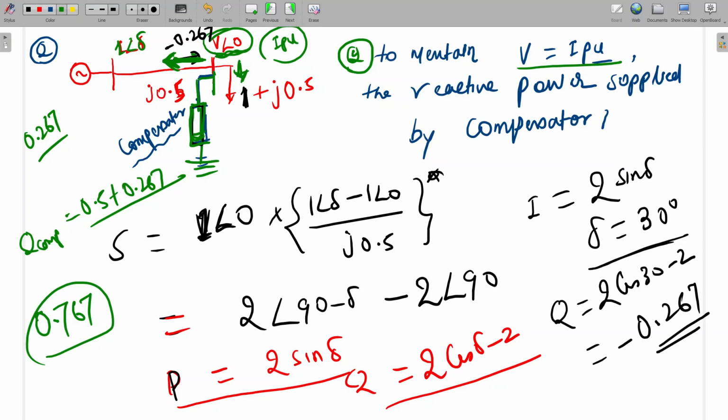So every time when a power flow question is asked, we should calculate the apparent power equation at the node where we are. I am doing power flow nodal analysis here, so I have to calculate the equation here. If some source is connected at that bus, we should do the VI conjugate with respect to that bus. After that, we can equate the powers, do the nodal power analysis, and get the final reactive power answer.